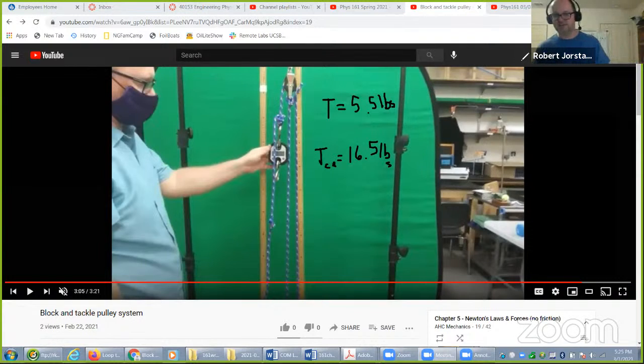And then you get a really, really long rope or chain, right? And then you could pull a whole bunch of chain over and over. And then you could raise the engine block very slowly by applying a force that a normal human could lift. And then once you get it lifted, you could tie that chain to a small object and it won't go anywhere because it takes very little weight on the other end of the rope to keep this thing from falling down. So it's a practical force distance trade-off.